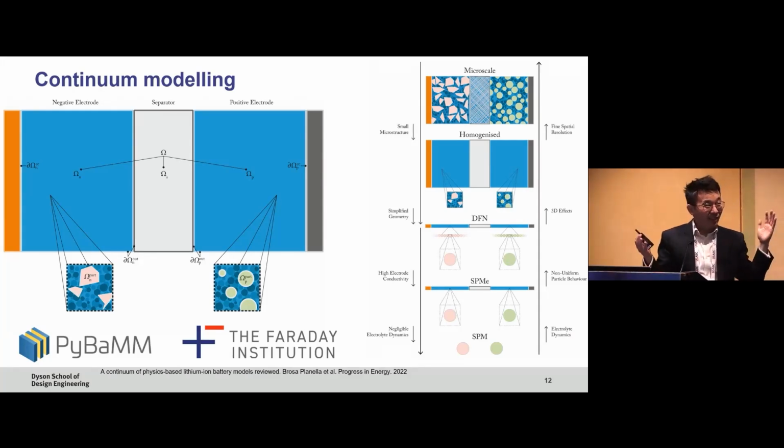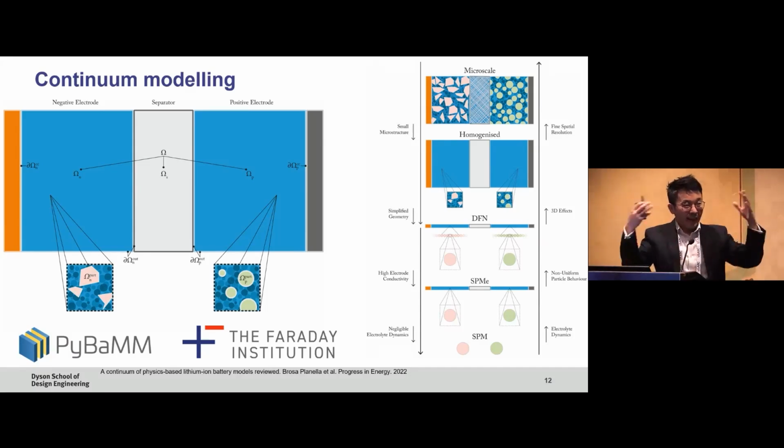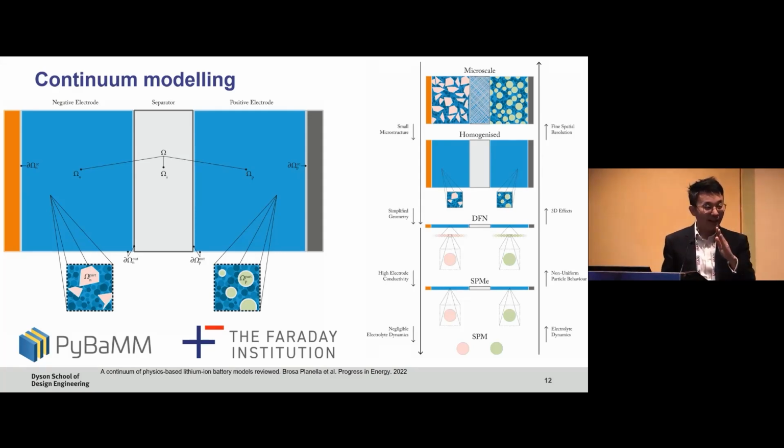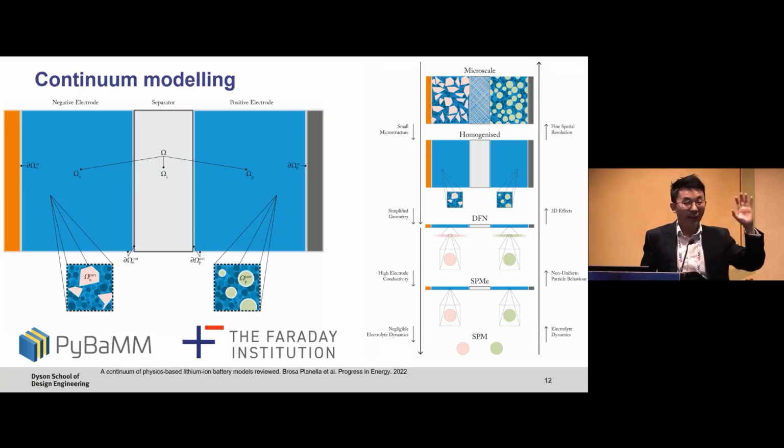Then you're unlikely to solve a full P2D model or Newman model in an entire battery pack. So you might do some model order reduction techniques, such as single particle models and more advanced techniques. I think it's also important to think about what you care about at the end. So it might be lifetime. And then in your models, think about what are the stiff parameters. You could argue a Newman model is ill-posed because there are 50 parameters and you're never going to be able to parameterize them all. But there are certain parameters in that model which highly define the future lifetime of the system, and there are more floppy parameters beyond that. So you need to understand how uncertainty propagates through your system, and then design your model order reduction around what you want to get at the end, and the areas that you neglect and the areas that you focus more on. So hopefully that gives you some indication of our thinking.